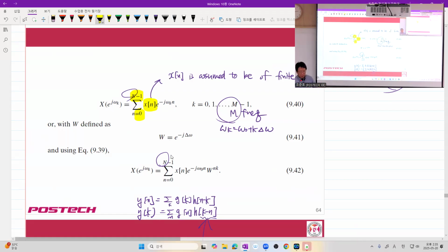I've repeatedly told you. And here, unlike the Wikipedia, where they introduced the chirp Z transform, the textbook has the chirp transform, which has the complex number Z sub k with unit magnitude. That's why there is no exponentially increasing or decreasing magnitude.